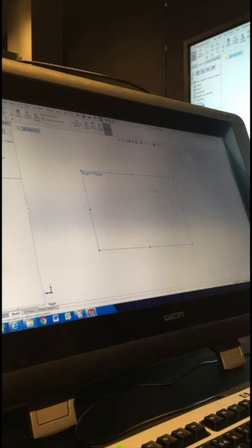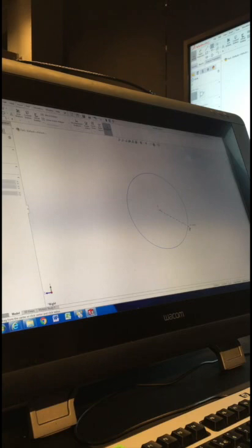So mouse gesture to the right to get the circle tool. Click on the origin, which is that red arrow. Now when you're clicking and dimensioning and sketching, it's really just click, let the mouse button go, drag out, click again, and that creates your circle. All right. And then zoom out a little bit, and then up above that circle, create another one at the top that's a little bit smaller.